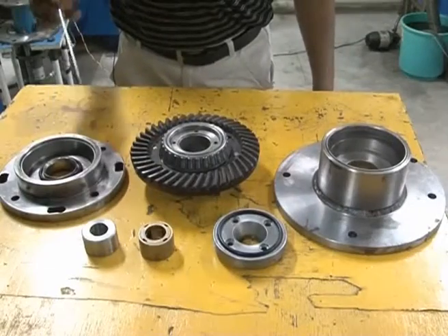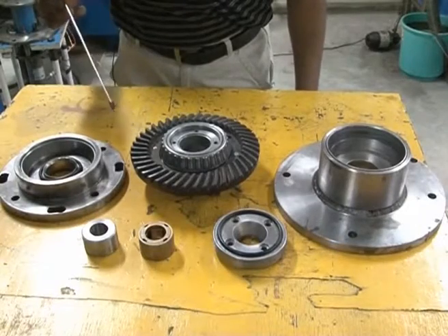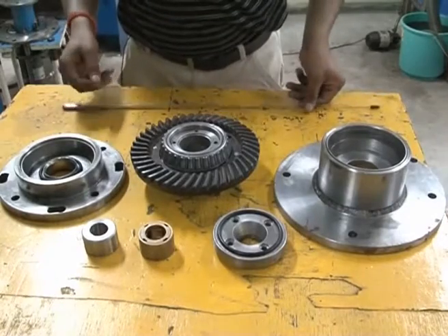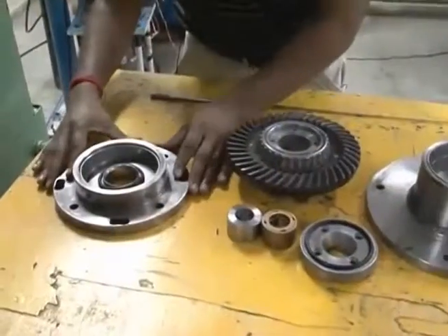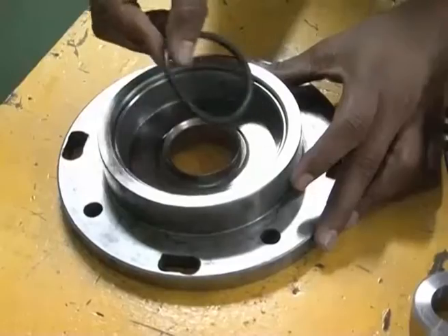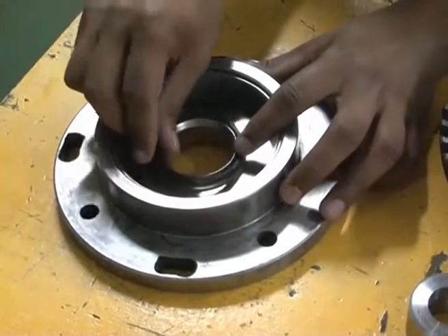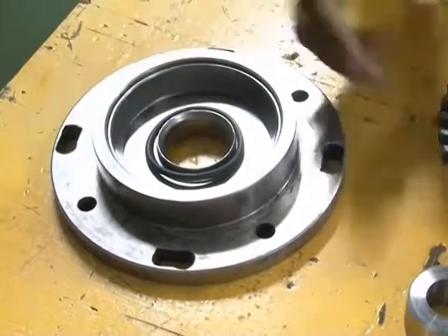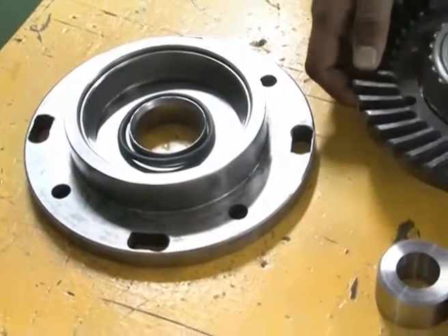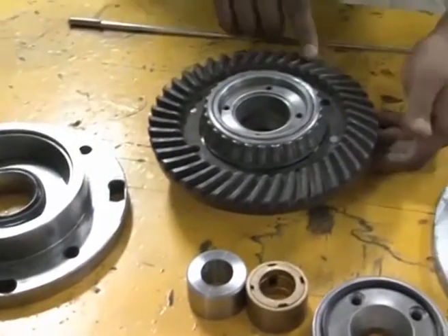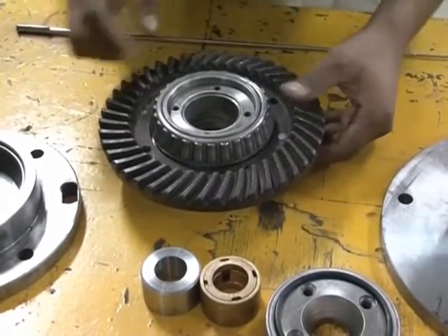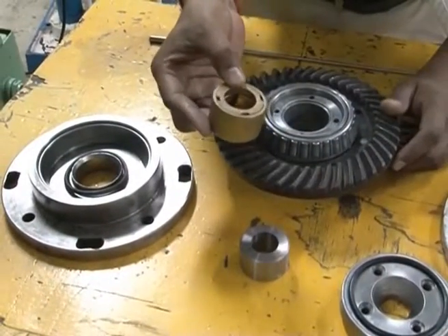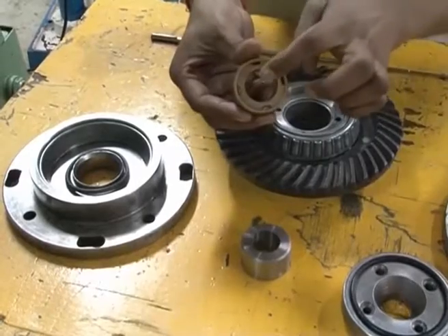Now you are seeing the rotational tooling that we are using in the universal rotational abrasive flow finishing process. The inner details are: this is the bottom plate, which has a curved surface where we place the O-ring to prevent leaks, and this is the crown that is made specially for the rotational system, and this is a workpiece holder where you have the workpieces.